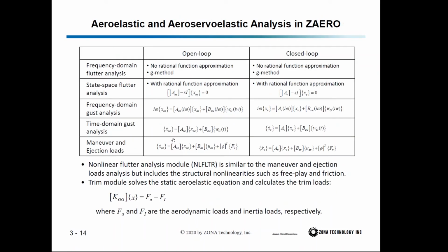In ZAERO, we can perform the Flutter analysis in the frequency domain or in the Laplace domain. So we can go to the state space analysis for both open loop and closed loop. And we can perform frequency domain and time domain gust analysis for both open loop and closed loop.